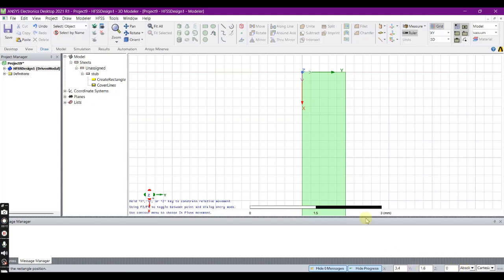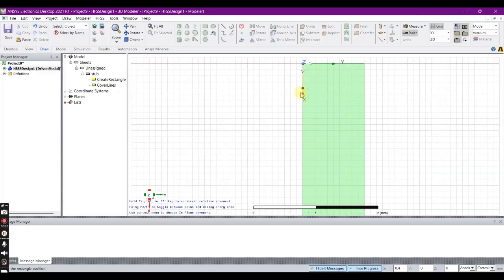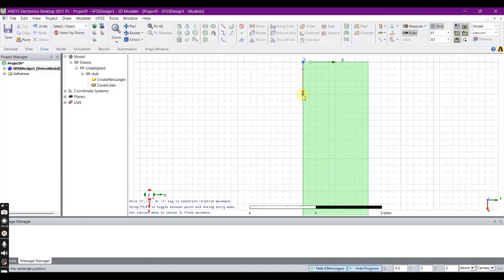Every time I am plotting, see the coordinates at the bottom right. So the first finger is 0.5 mm from the top. So here, see at the x axis, it is 0.234. Now this is 0.5. So the starting coordinates are at x axis 0.5, y and z should be 0.